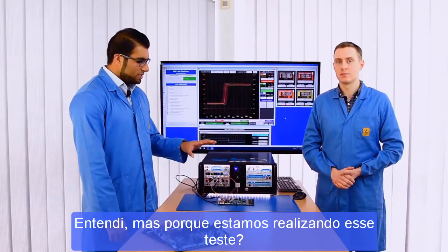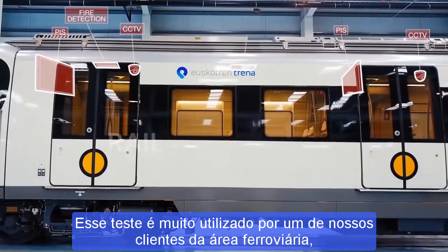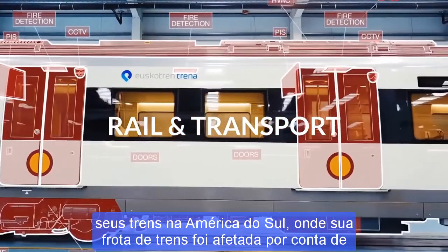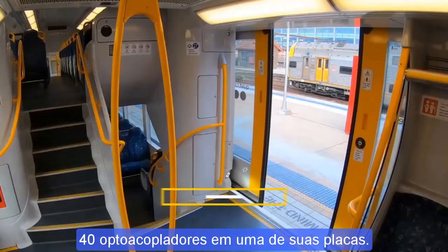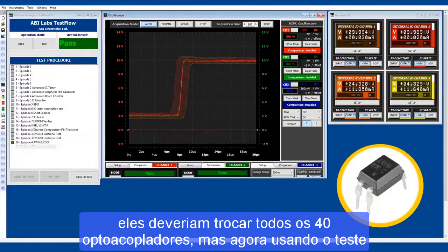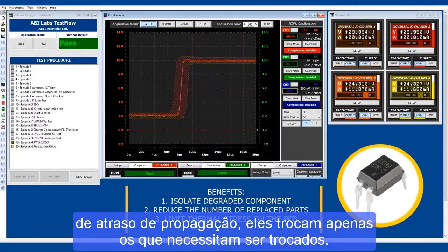I see. So why are we doing this particular test? We had a customer in South America, a railway company, and their trains, their fleet were being affected by the 40 optocouplers on one of their PCBs. So to repair that in the first place, they would have had to replace all 40 optocouplers, but now they're just using the propagation delay test to check which ones specifically need changing.